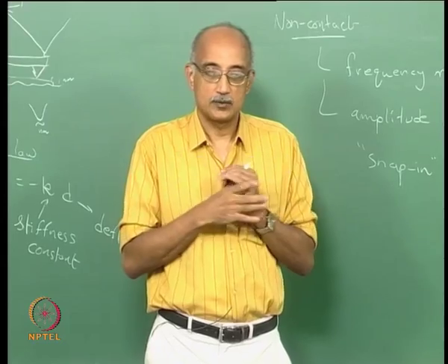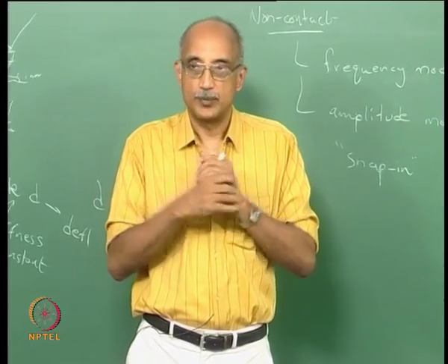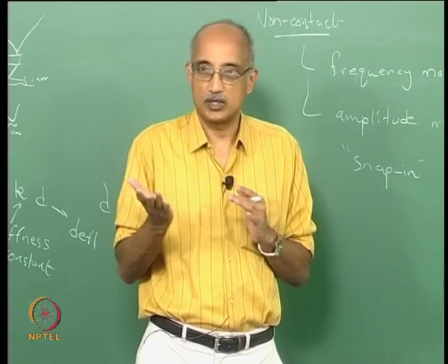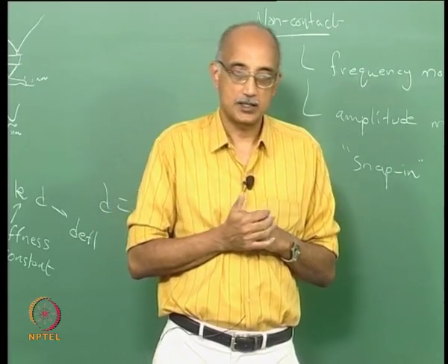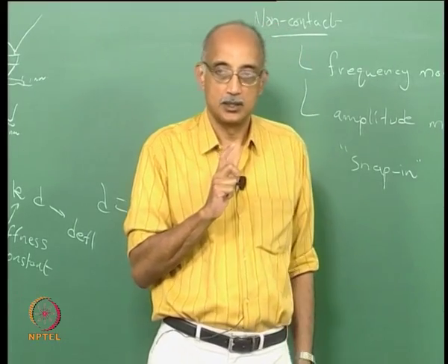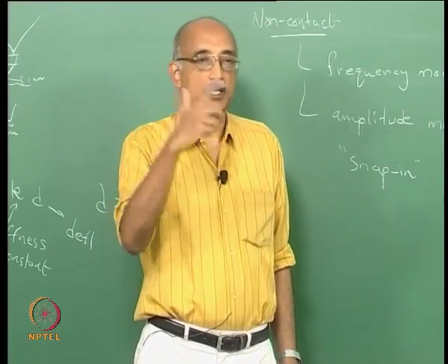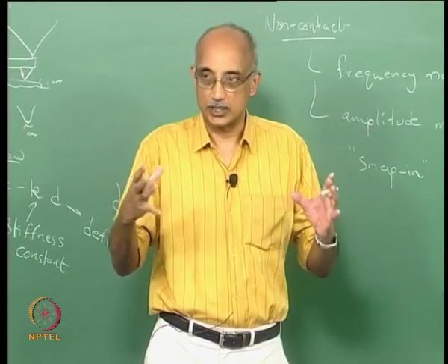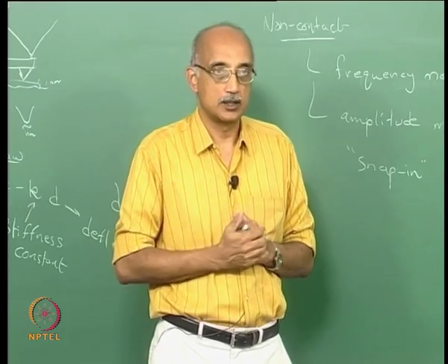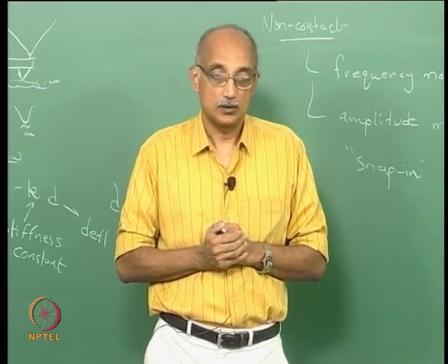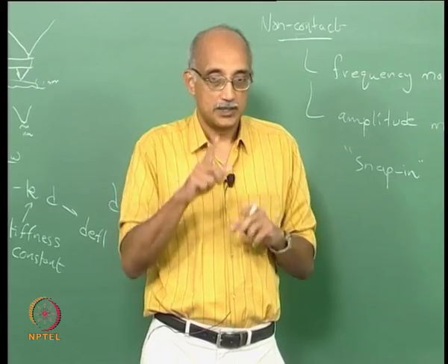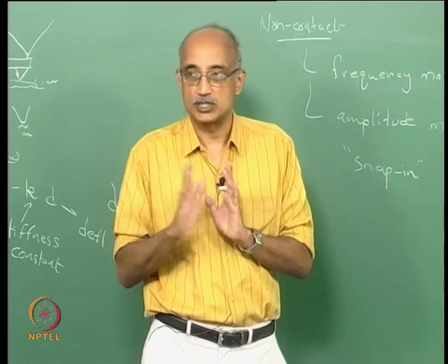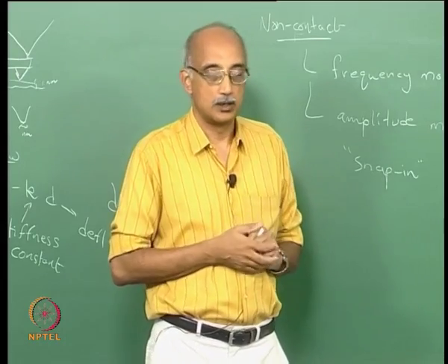So it's like, if you can represent a brick wall by simply looking at one brick, that's exactly what crystallinity is. It essentially says if you can identify a single unit cell which if duplicated in 3 dimensions will produce the entire structure of the material, then you can call it a crystalline structure. One key thing to remember is these 3 dimensions do not have to be orthogonal to each other. So, that is one way in which it is different from the simple brick wall analogy.